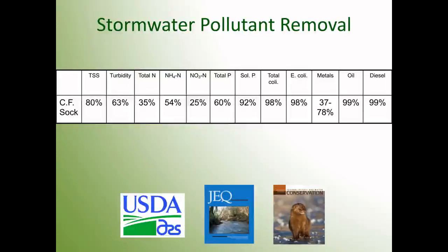And then finally, one of the other key differences in the type of media or material that you can put inside the containment system will allow you to target different types of pollutants that we find in post-construction stormwater. Now, some of these natural materials or organic materials are relatively inert, and they're designed really to target sediment through physical filtration or physical sediment deposition means.